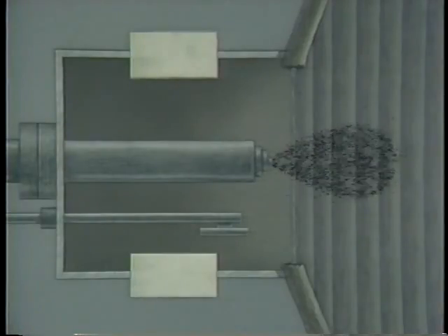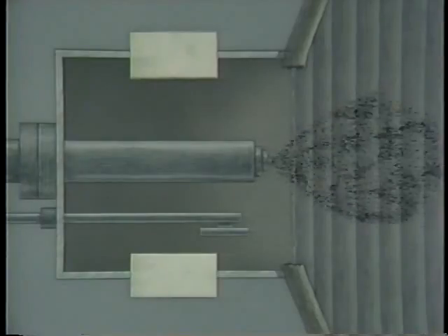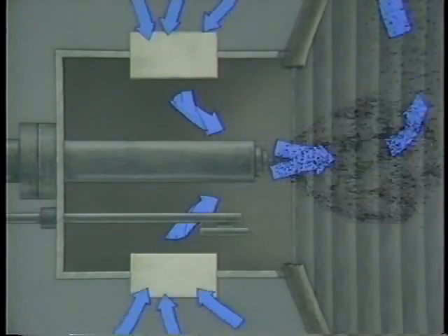Unless the fuel flow is immediately stopped and the boiler is purged, an abnormally high concentration of fuel may accumulate near the burner port. If airflow is subsequently reestablished, this large concentration of fuel can ignite suddenly and cause an explosion. Interrupting fuel flow will also extinguish the boiler flame, and unless steps are taken to correct the problem according to procedures, an explosion may result when fuel flow is restored.